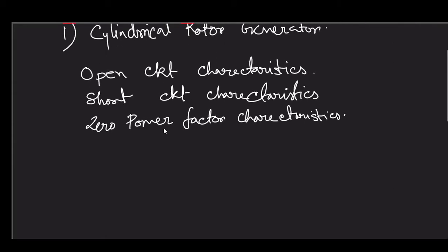First of all, how can you obtain open circuit characteristics? It is very easy. I am drawing a very crude schematic diagram of the connection of the open circuit test. Suppose this is my stator of the generator having three phases. We are assuming a balanced stator winding.